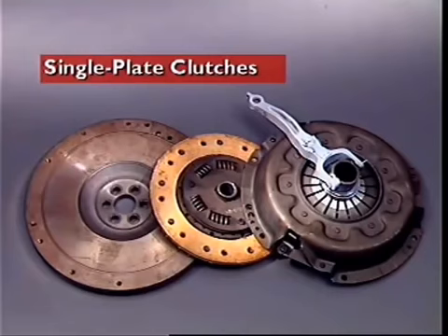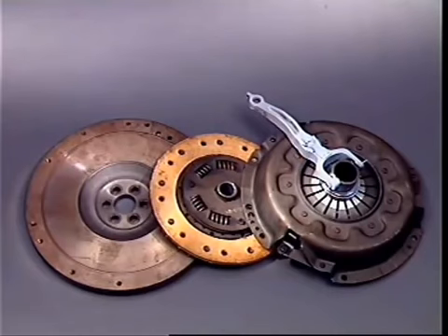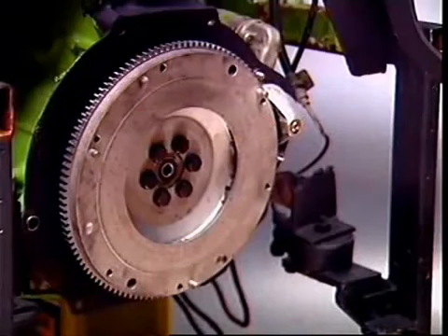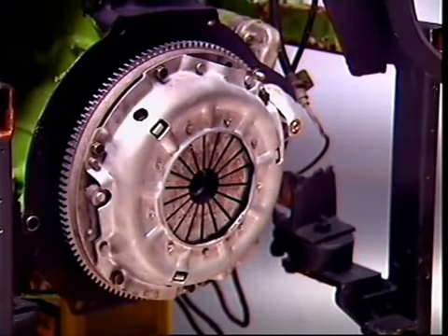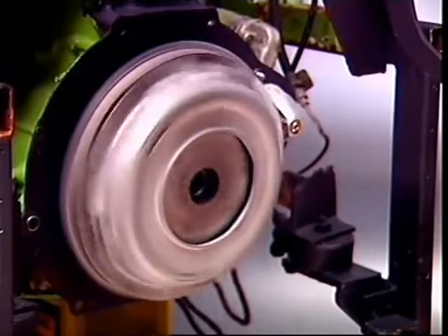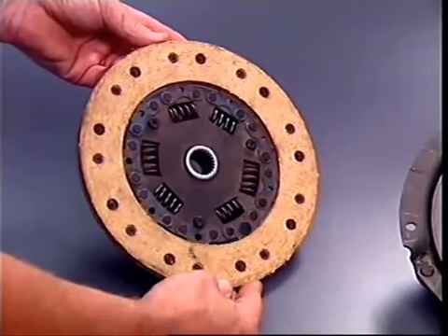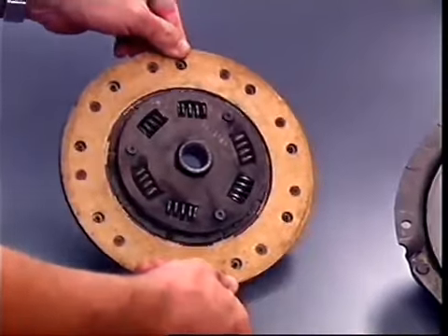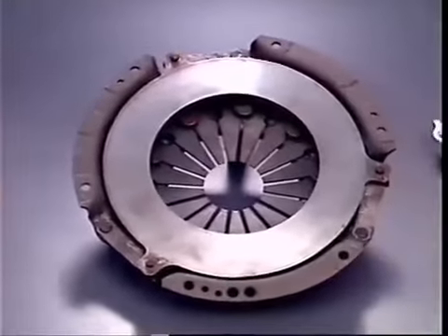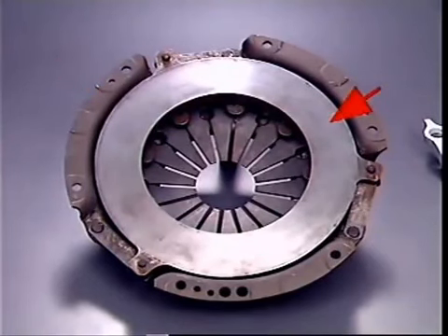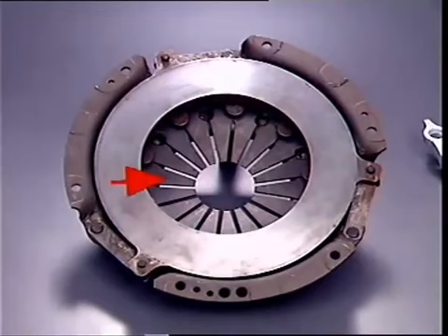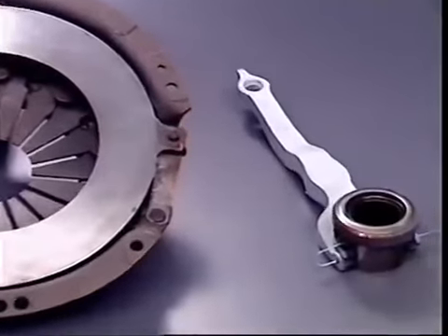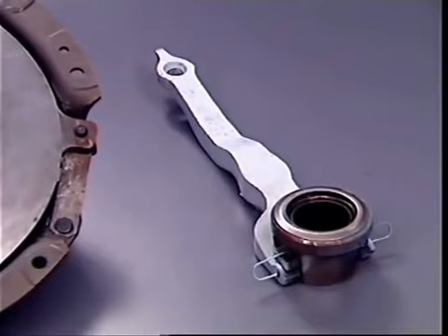Most light vehicles use a single plate clutch to transmit torque from the engine to the transmission input shaft. The flywheel is the clutch driving member. The clutch unit is mounted on the flywheel's machined rear face, so that the unit rotates with the flywheel. The clutch unit consists of a friction-type disc with two friction facings and a central splined hub, a pressure plate assembly consisting of a pressed steel cover, a pressure plate with a machined flat face and a segmented diaphragm spring, and a release bearing and operating fork.